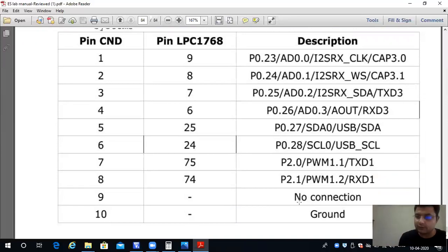So whenever you start with any program and you want to think about connections, that is, how to actually connect the outside peripheral with the microcontroller, you have 4 connectors. Out of those 4 connectors, for every port pin, the first function is the GPIO function. Every port, every pin, you will not be able to connect through these connector pins. So which pin to use, you always consult appendix C.